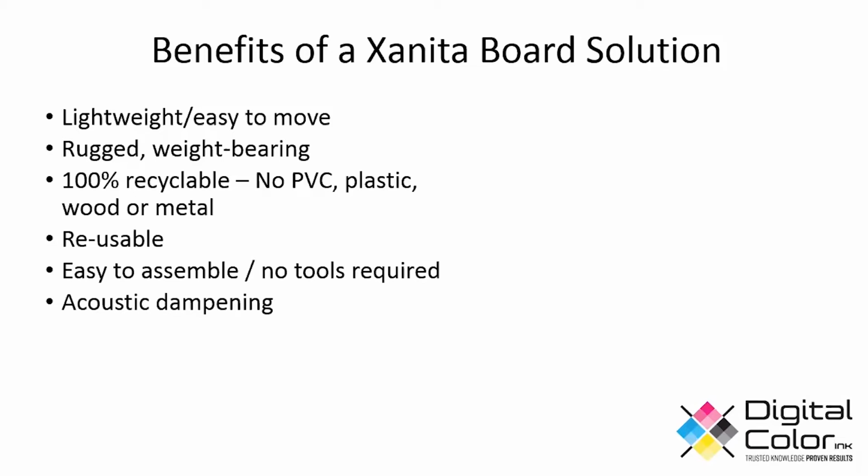Xanita did that testing, but Crew, I don't have that number right off the top of my head. I will get it, but let's just say it was more than 600 pounds load test. Because you've got all that support when it's laying flat, and then when you stand it up, you've got the back brace, which is made out of Xanita board. And keep in mind, Xanita board can hold up to 5.6 tons per square foot before it crushes. So it's really a strong product and designed from a load bearing point of view.